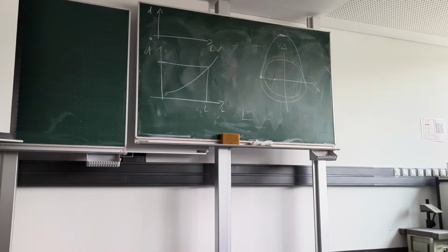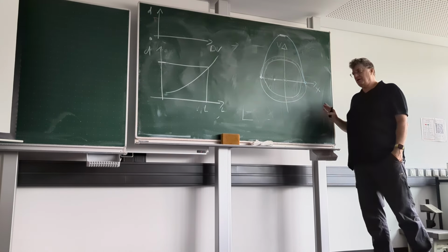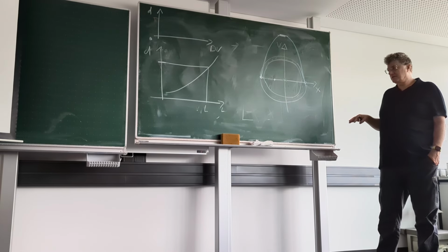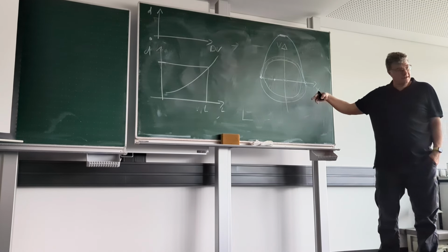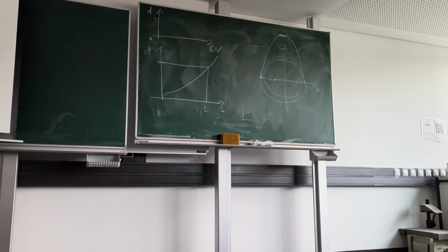And if you try to simulate this thing, you definitely need to use boundary layers. Depends if COMSOL already introduces those boundary layers on the frequency. So you see that's not always so easy. You not necessarily need boundary layers in electrical problems, but under certain conditions. You see it also depends on the type of analysis.